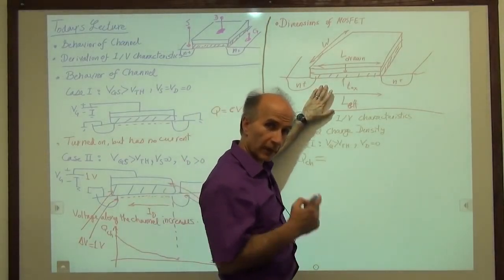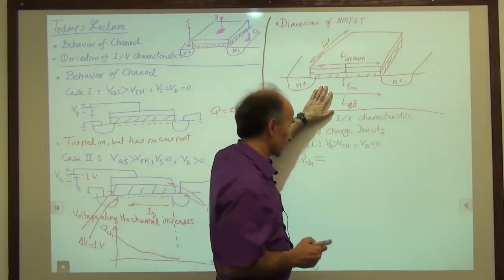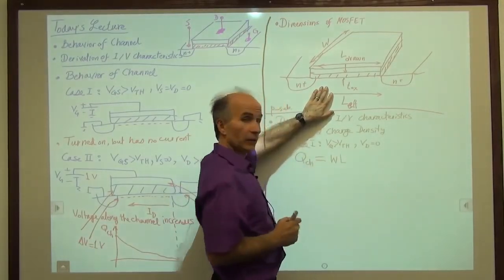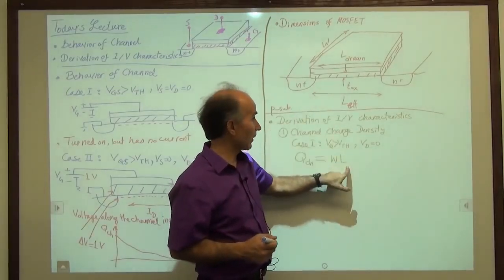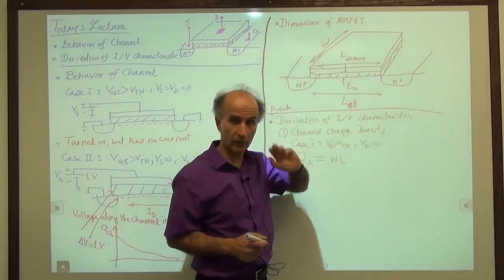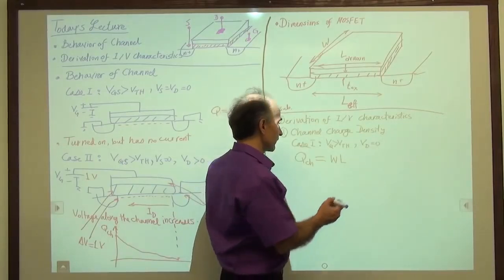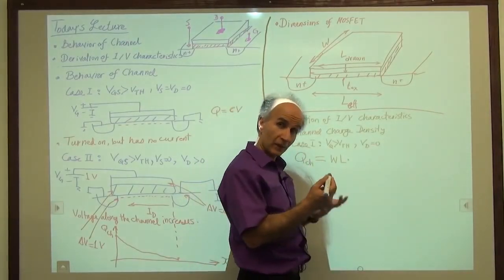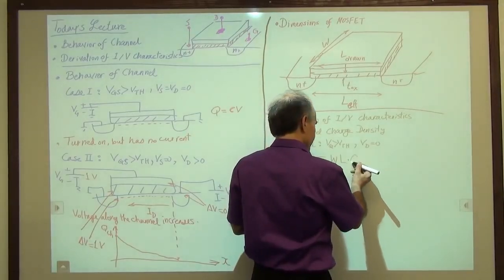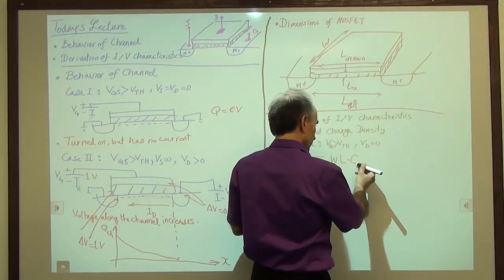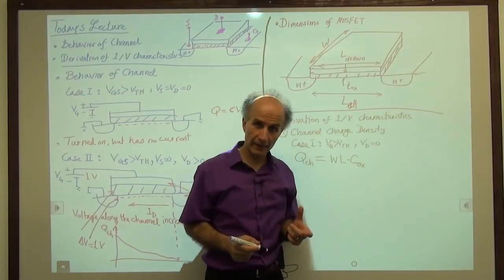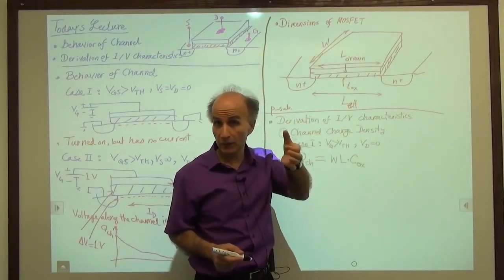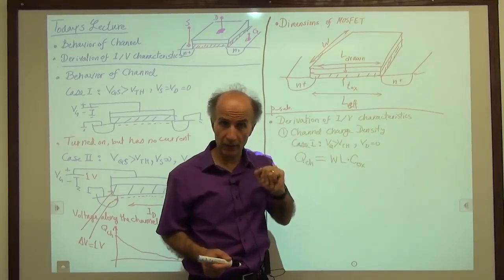So how much is the capacitance? Well, often in our analyses, we write it like this. We say the area of the device, W times L. L from now on indicates effective L, so just remember that. Area of the device times some quantity, which is easy to find, and that's called Cox. Cox is the capacitance of the structure per unit area, per meter squared, per micron squared, whatever you like.